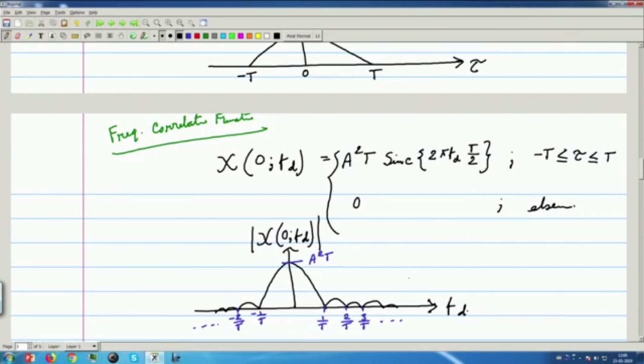It has a finite width, and the frequency correlation function has side lobes that keep extending, though diminishing. So, there is a chance that it will disturb the detection process, because it will affect all subsequent targets. This should be avoided if we can give a better design.